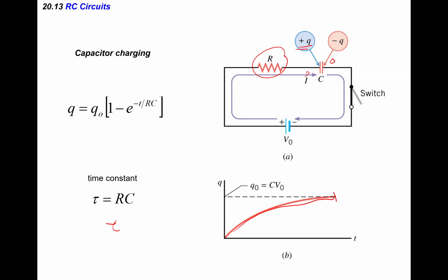Our capacitor is the same. See this 20%, from here to here, this little 20% takes this amount of time. But think about this little part in the middle. Maybe 50% also takes this amount of time. You will see this amount of time, they are almost the same. So like if you charge your car, if you have an electric car, usually we charge to 80%. Usually it's the most effective way to charge, so it takes less time to charge.